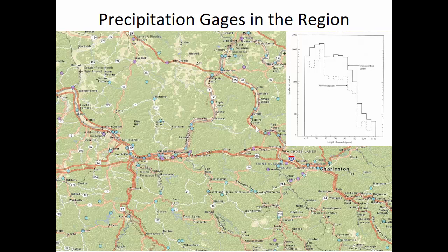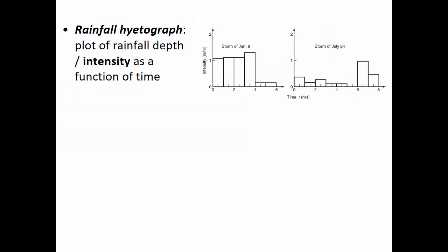So there's really a lot of statistical regression and extrapolation that happens when we're trying to create intensity, duration, frequency curves. They're originally based on real measurements of rainfall, but the problem is that America is such a big country and we have so few rain gauges that go back very far that you have to do a lot of guesswork to come up with the storm size that you're going to use to size a lot of the storm drains and culverts and drainage ditches and so on.